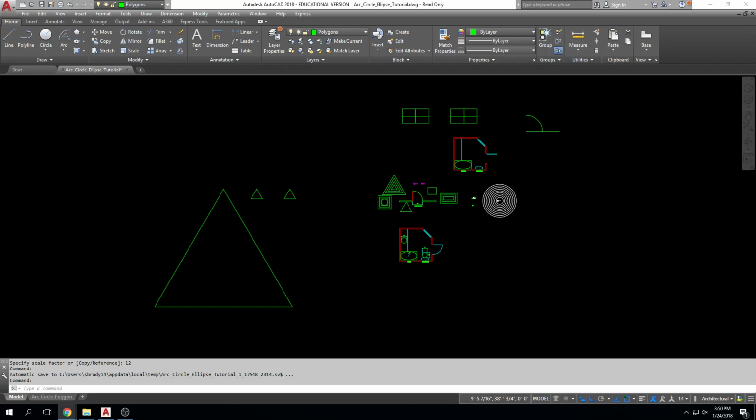But the way that we look at a floor plan is we cut the floor plan at a height of about 3 to 4 feet, right? So between 3 and 4 feet, that horizontal cut, the items that we touch in that cut are illustrated on a floor plan, right? So that's why when we see a floor plan, we're not seeing lights on it, right? Because a floor plan is cutting the floor plate at 3 to 4 feet and looking down, okay? The walls are the heaviest, windows and doors are next, furniture, floor finishes, it all grades down from there, okay?